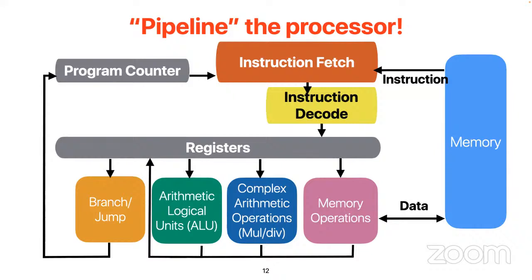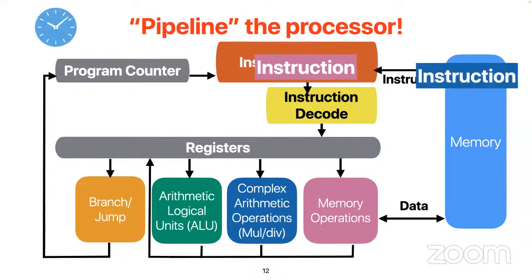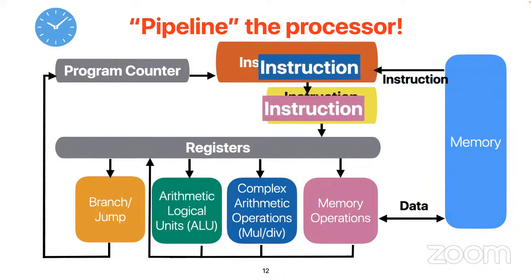The pipelining idea is that we have the instruction make partial progress every cycle, because every instruction only has to move through part of the processor, so the cycle time could be set really short. In each cycle, we may just want the instruction to go through the instruction fetch stage, or go from instruction fetch to decode, and you can yield your fetch unit to fetch another instruction.